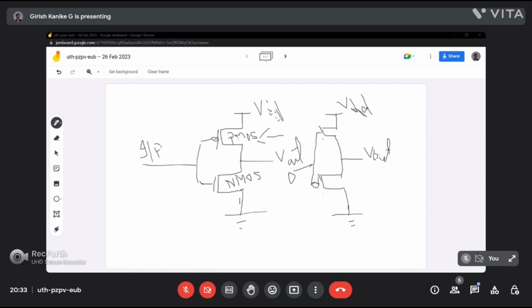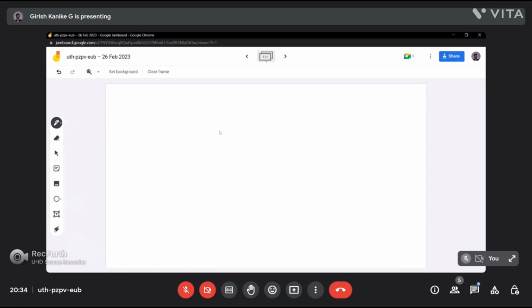Okay, I'll conclude the answer. Actually, Praveen, the result you are saying is correct, but PMOS passes perfect 1. Ayush, to explain in a simple way, if PMOS passes perfect 1, it allows perfect 1 to flow. So this perfect 1 will flow here. It opposes the perfect 0. So if it is 0 here, you are getting 1 here. If you are providing 1, it provides 0 because NMOS passes perfect 0. You both said one part of the answer correctly and the other part wrong.